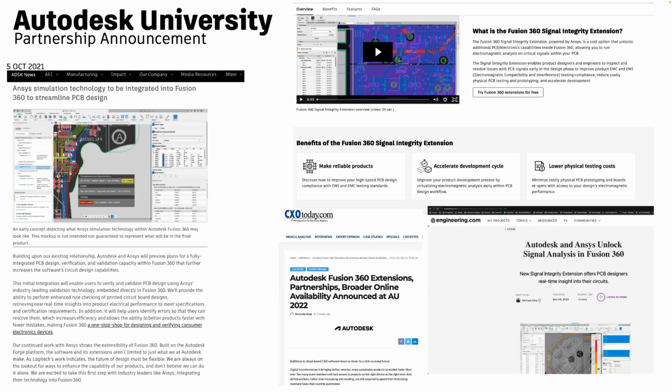So we've had some integrations with various signal integrity tools. And foundationally, the tighter coupling between signal analysis, signal integrity, circuit analysis, your classical SPICE simulation, and things like design rules. Every EDA application on the planet expects you to go from a circuit-minded view of a problem to a geometric view of a problem. Simplest example is the distance between things. What are we talking about when we talk about the distance between copper features? We're talking about the capacitance and the electromagnetics that are hovering around the signal path.